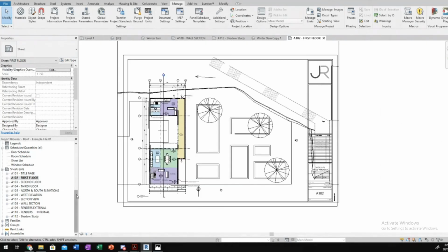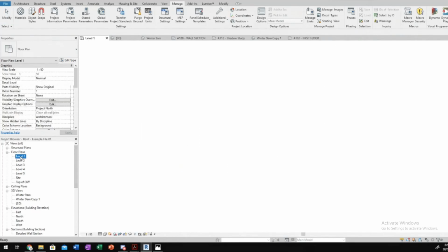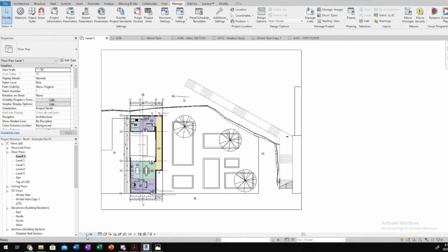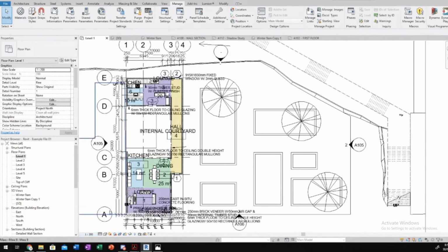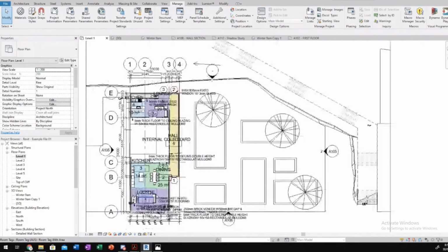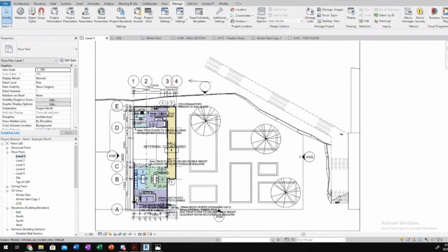So yeah, one thing I want you guys to be careful of, if we go back to this with our scaling, if we change our scale, say, to 1 in 100, so look what happens with the text. It's changed size automatically. What if we go to 1 in 200? Again, look at all of that. So basically what happens is with line weights and text and annotations, it scales for the size of the...